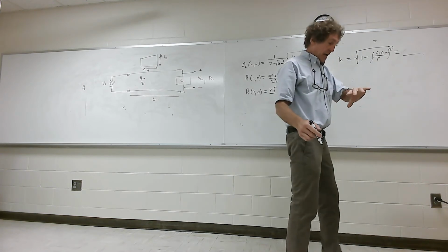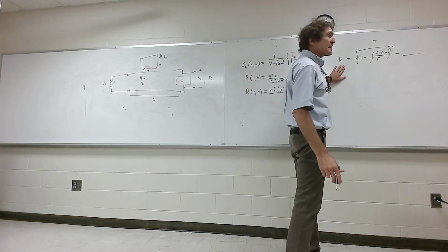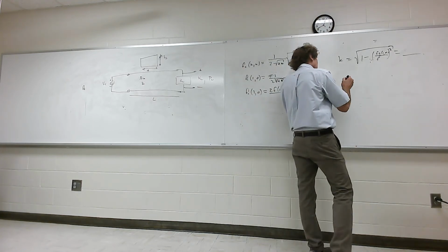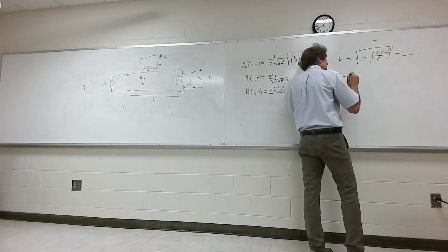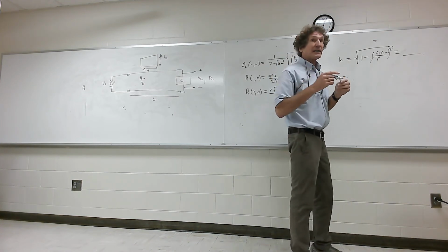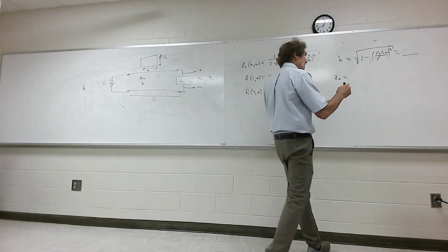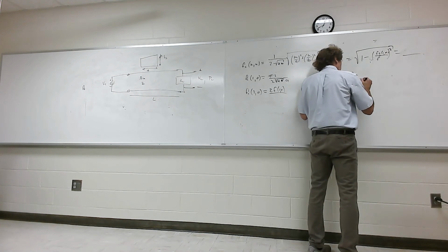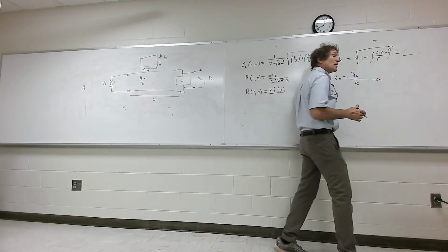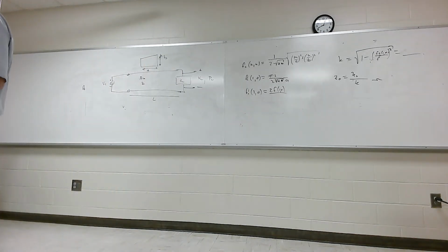Okay. Give me another minute or two. Just hang on. So once I get the value of k, now I get the value of the impedance, right? And if it is a TE mode, then it's going to be what? The waveguide impedance. I'll make it air so it's just eta 0 over k ohms, right? It's going to be greater than 377. Y'all follow me on that? Once I have that impedance, then what do I do?